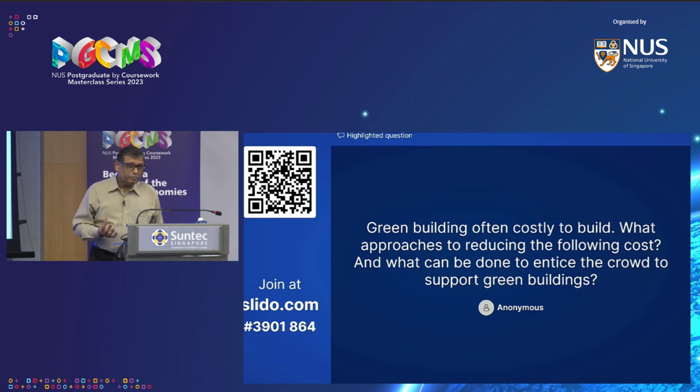When you design buildings where you reduce the energy consumption at the demand reduction stage, passive design, maybe you're investing in some building material. Now think about it, that material of the facade or the window panel is there for the next 30, 40, 50 years. When you apportion the cost over time, first cost, maybe. Even then I would argue it need not be. But if you do a life cycle costing over the life of a building, it pays itself times over. And I think it's an argument that really needs to be understood as to where the thinking is coming from.